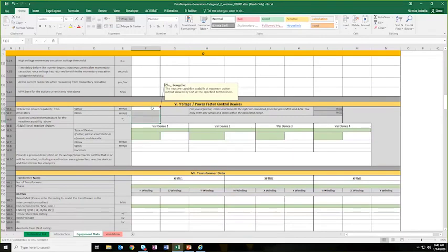We want to show, by comparing the two, that it doesn't show this number cannot be achieved. If we find from the test report, for example, that the test is performed at a lower temperature and cannot even achieve this Qmax, Qmin, then we'll definitely see this Qmax, Qmin is wrong. But if it's the other way, the test is performed at a higher temperature and shows a smaller capability, then we have to use some judgment.